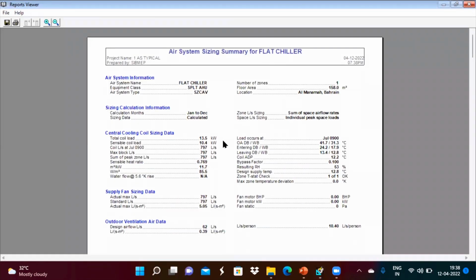Currently, the contribution to the chiller unit is reduced to 13.5 cooling kilowatt, that is 3.83 TR according to HAP calculations. That is around 46% less than the VRF capacity. Remember, here we have not considered partition within the floor, diversity in equipment load, and diversity in lighting.